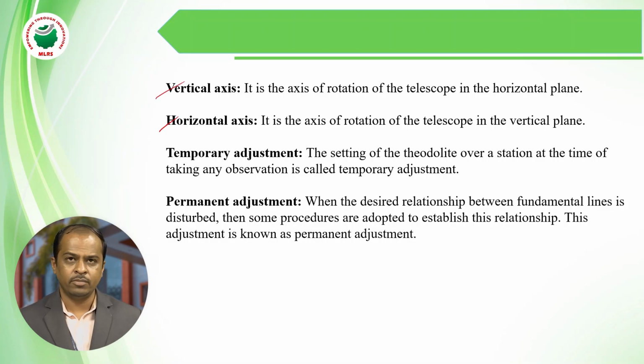Temporary adjustments are made at every setup of the instrument. After every setup of the instrument, if we make some adjustment, that adjustment we call a temporary adjustment. And the permanent adjustment is one that will be disturbing a relationship between fundamental lines.